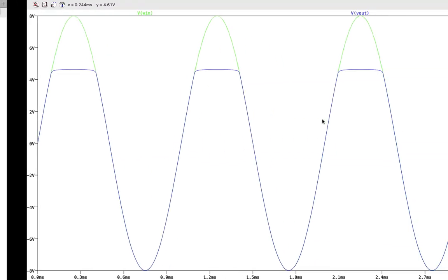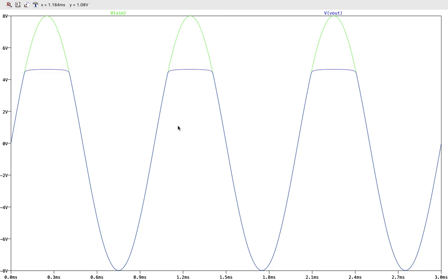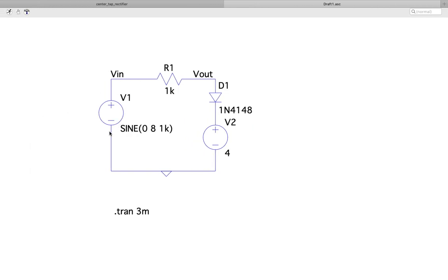So now we want to get the voltage transfer characteristics, VTC. For the voltage transfer characteristics, what we are supposed to do is slowly vary this input VDC, maybe from a negative voltage, say from minus 8 to 8 volt. So I'm slowly increasing the DC. Then how will my output look? It's the V in versus V out curve.